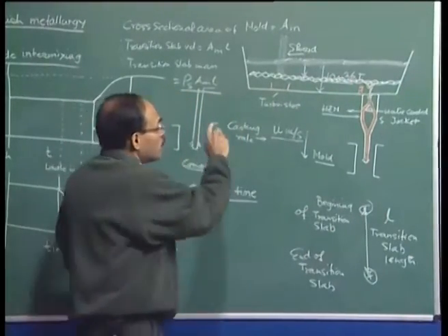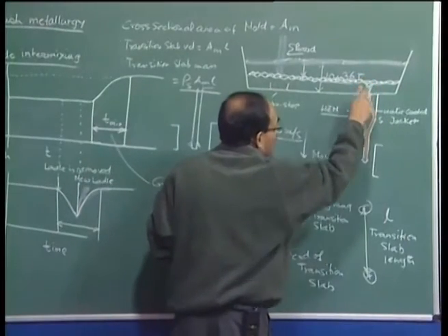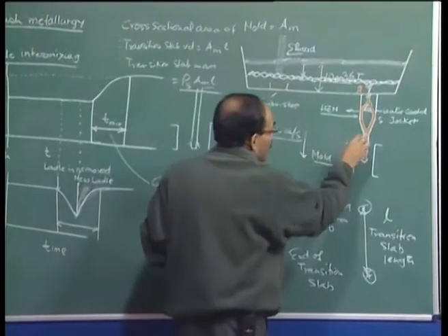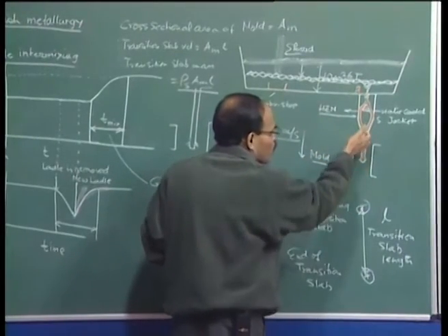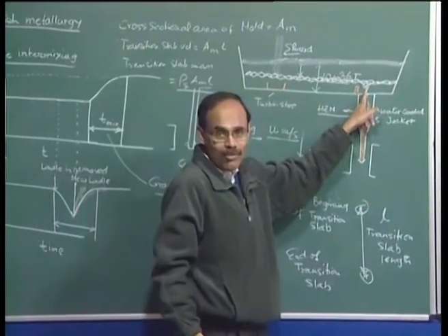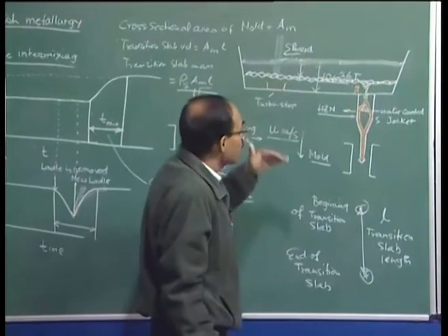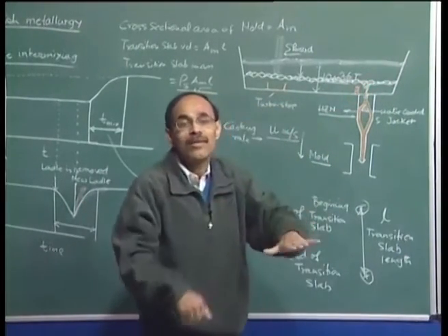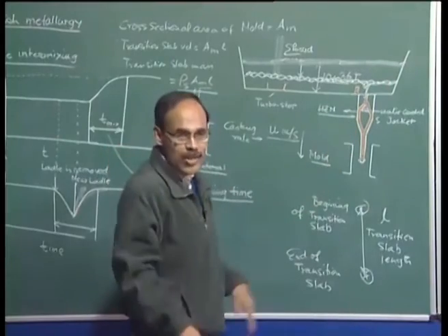Okay? If you don't stop the casting, what happens? Slag will be entrained, and this slag, which is oxides, is going to make steel weaker, and as a result we can have innumerable problems. And of course, nobody is going to buy that steel which will contain a lot of entrained slag particles. So, the moment slag starts to be entrained into the mold, it is at that point that we say the casting of this particular sequence is over.